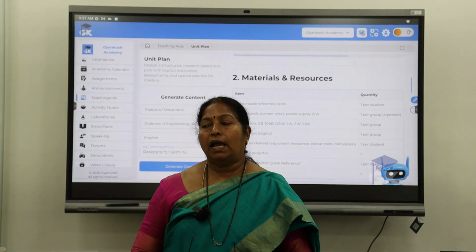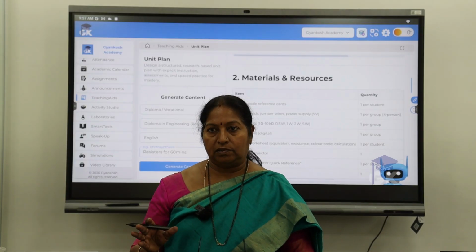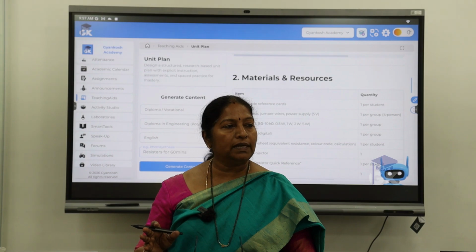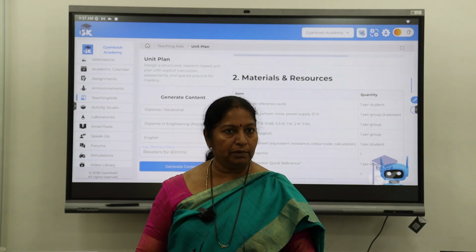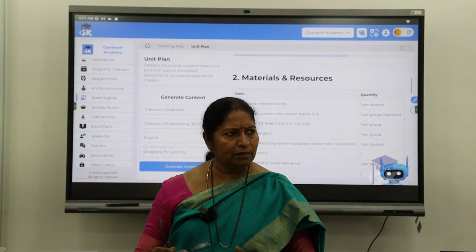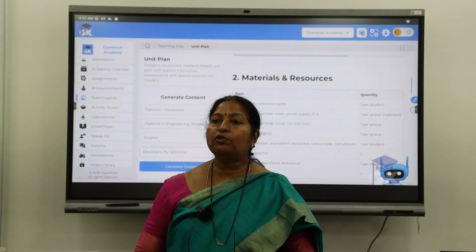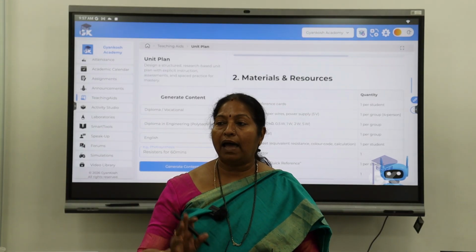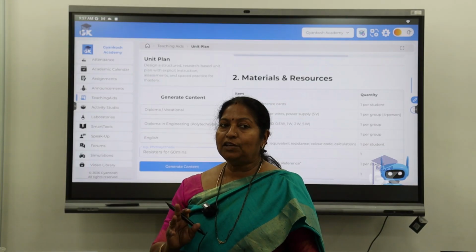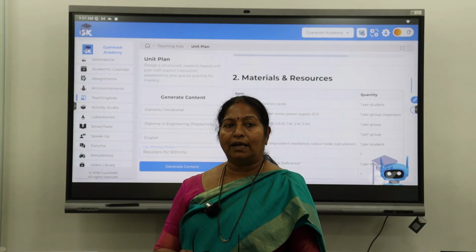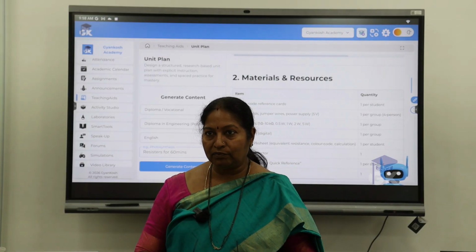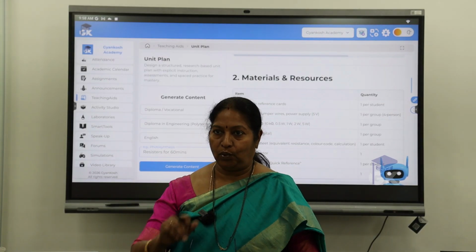Now I'll also give you a group of resistors of the same 1K. You need to measure each and every resistor with the multimeter. The color code will say the same, right? Tolerance will also be the same. But if you measure with the multimeter, the values will be different. Then you comment on that, analyze and tell me why it is so. That is one of the exercises after this color coding.